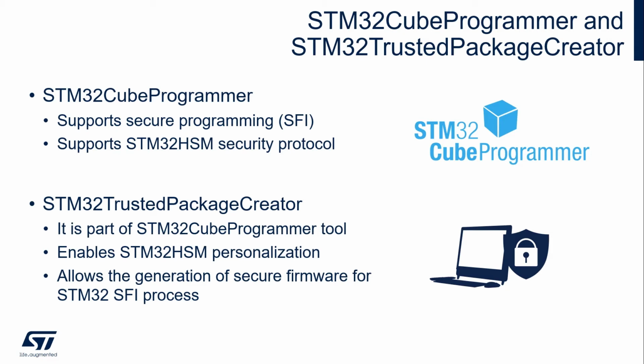During the installation of STM32 Programmer, you have the option to add an additional software, STM32 Trusted Package Creator, that actually enables the SFI process. STM32 Trusted Package Creator comes with both a graphical user interface and a command line interface, and can be used to generate the SFI files and to provision the HSM module.